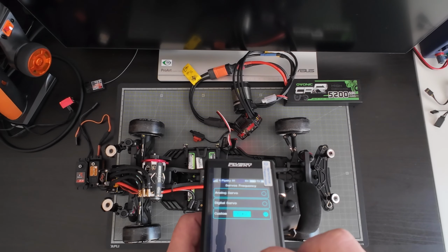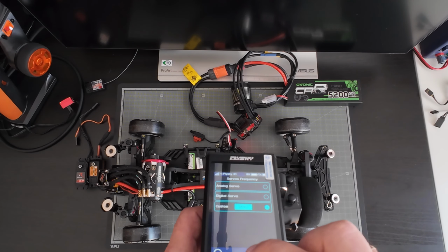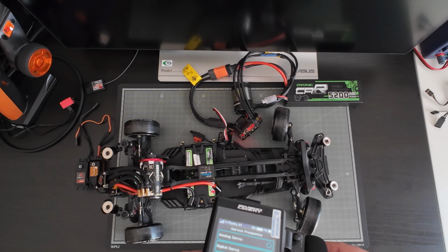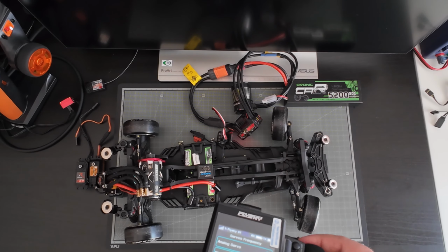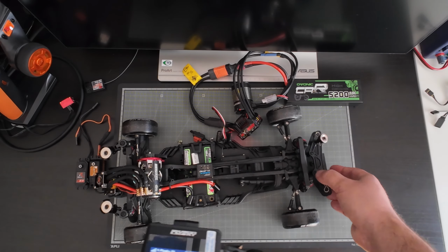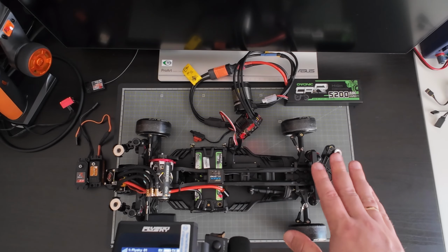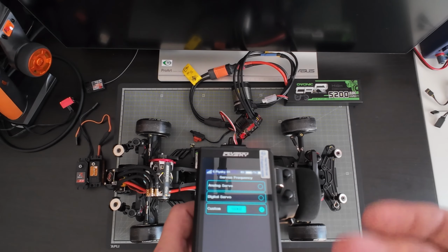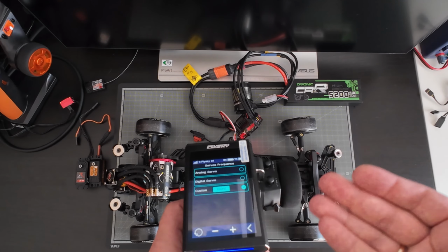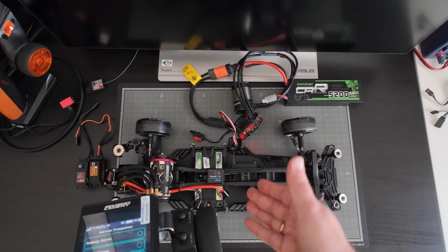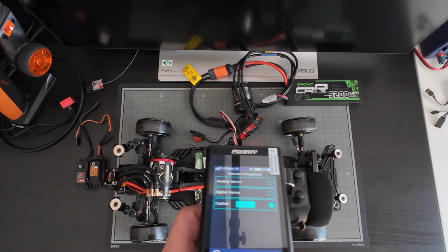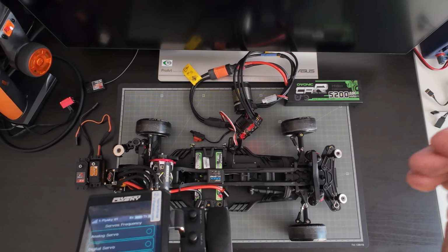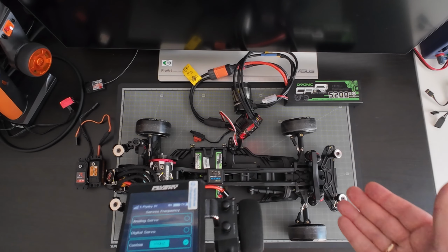When I go to, for example, 150, so let me put 150 Hz, sometimes it works, but sometimes I noticed that even at 150 it was experiencing problems, okay? So that's how it's working. This is proof that our theory about the frequencies is correct. This specific servo can hold up to 140 Hz, and everything over that has issues.